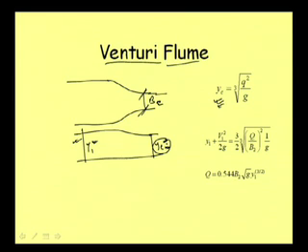Now, what we can do, at upstream the energy E1 is equal to 3 by 2 cube root of q square by g, that expression, and then already we have written in the last page. So, similarly we can write that E1 is equal to y1 plus v1 square by twice g, and 3 by 2 cube root of this q square, I am writing as (q by b2) whole square by 1 by g. B2 means this BC, we are talking about section 2, B2. Okay.